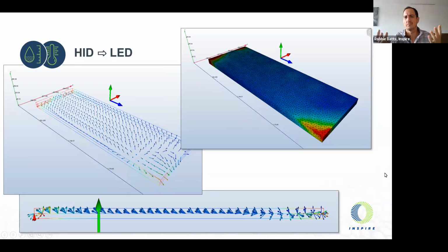The change is monumental. So from a temperature perspective, up on the top right, we can see that the temperature is very even across the board. But the demonstration of the vectors here is so important to us to understand that we get almost 90 to 95% of the air getting up and out of the canopy as quick as possible. It makes a huge difference, and these are very minor changes, and definitely something you need to consider for a retrofit application. Whether you're having to buy more equipment or not, PPF match or wattage match, both these things need to be considered. Next slide.